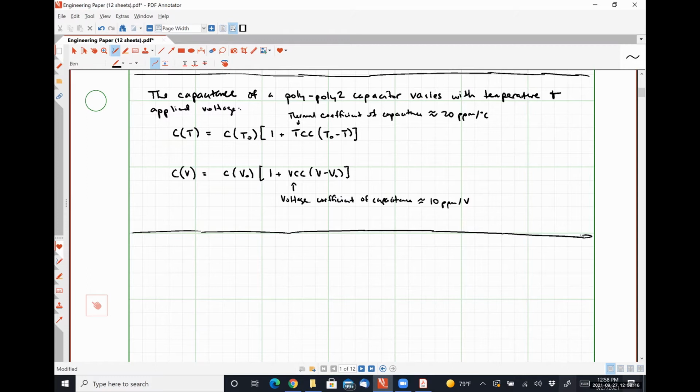Because the distance between metal layer 2 and the substrate is significantly larger, which means the plates are further apart of that parasitic capacitor. We are going to have some metal one involved in order to send our signals down to the rest of our chip and all that kind of stuff. But we can minimize that. But another really interesting way to do it is to utilize a stacked capacitor.